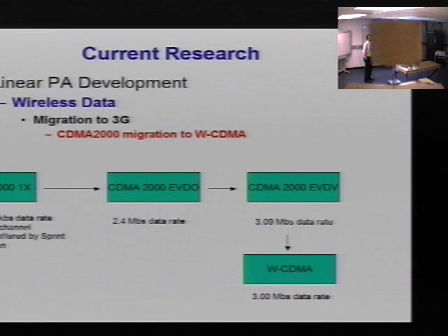Stefan, the real problem is that in IS-95, especially on the reverse link, when you have just BPSK or QPSK modulation, you're at almost constant envelope. While when you go to a higher rate and employ higher rate modulation, suddenly the peak to average issue is much more pronounced, so you have to back off from your power amplifier more substantially, and then the efficiency of the power amplifier just drops down.